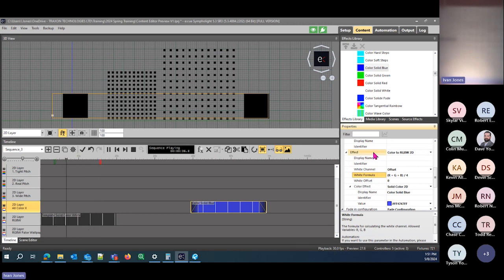Especially, it is important to note that some of our fixtures are doing this color conversion internally, and you need to know whether to turn that color conversion off by setting it into a different mode, or just settle with it and know that your color conversion is going to go through another color conversion, which usually is fine, but if somebody starts getting really specific about colors, you can end up with dramatic swings unexpectedly.